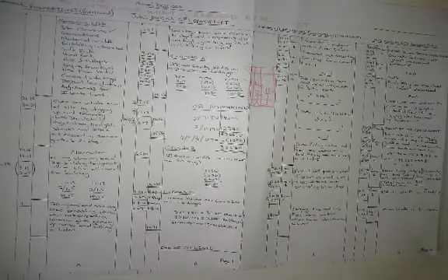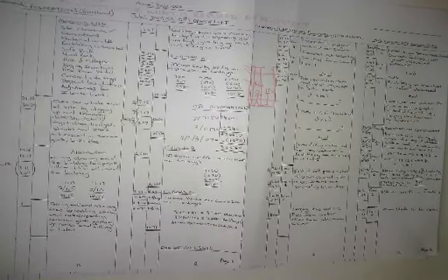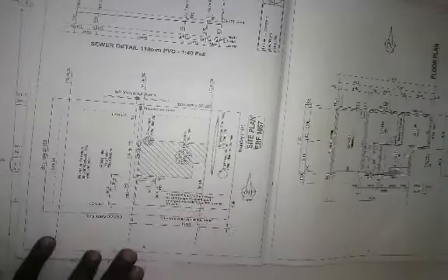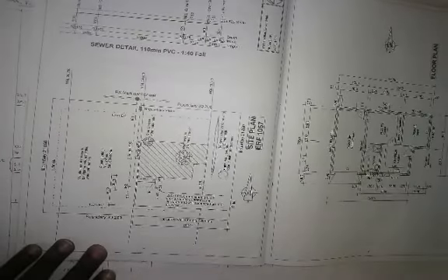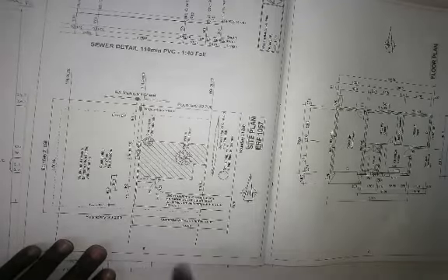Okay. So when they say clear the entire site, regardless of the shape of the site, guys, now you do not consider working space. You basically take from the footprint of your site, basically from your boundary, from where your site fence is, guys. Okay. So depending on what the instruction is, in this case, here is the site. Here's the entire site. It says clear entire site.